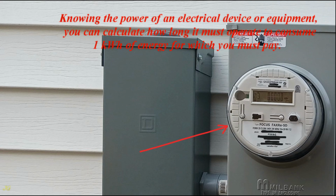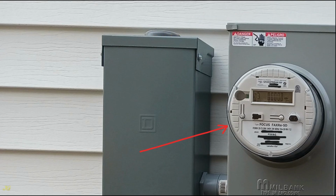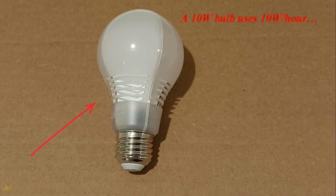Example. Knowing the power of an electrical device or equipment, you can calculate how long it must operate to consume 1 kilowatt-hour of energy for which you must pay. How long does a 10 watt bulb have to operate to consume 1 kilowatt-hour of energy? A 10 watt bulb uses 10 watts per hour. So 1 kilowatt-hour will be used in 1000 watts divided by 10 watts equals 100 hours. A 10 watt bulb must operate for 100 hours to consume 1 kilowatt-hour of energy.